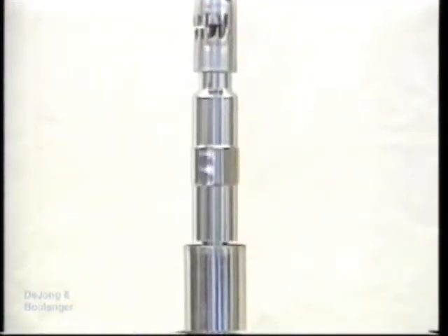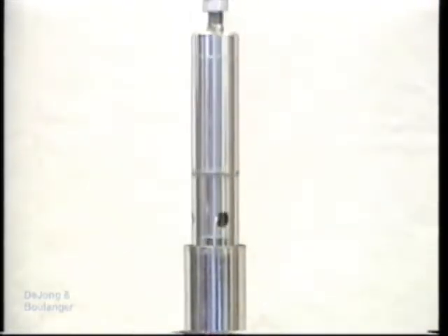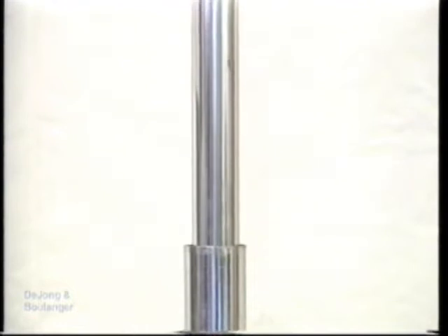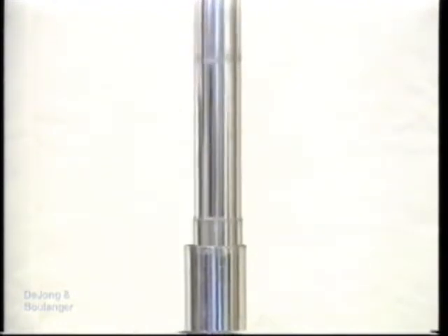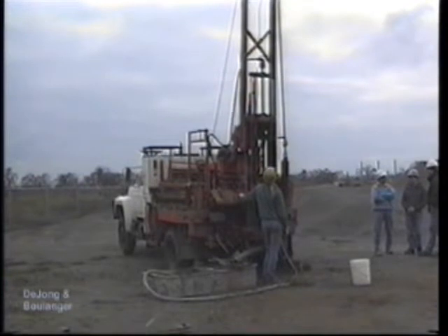Wireline retrieval systems expedite coring by removing only the full inner barrel from the hole, thus retrieving the sample while leaving the outer barrel and drill rods down the hole. The type of coring equipment and operating procedures can greatly affect the quality of the retrieved rock cores. Rock cores can be heavily fractured and damaged by the coring process.